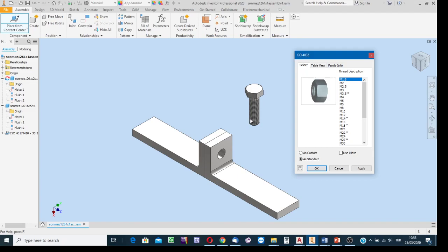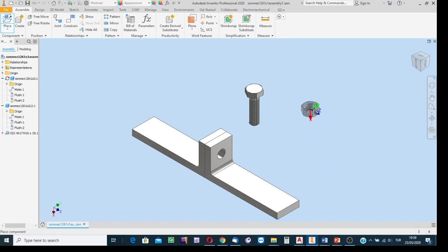The bolt is a 10 millimeter bolt, so the nut must be the same size. Metric 10 is the thread size, the measured diameter of the threaded part. It must be the same. No need to edit or modify the nut, so select the standard option, not custom. And then locate the nut in the vicinity arbitrarily with a click.